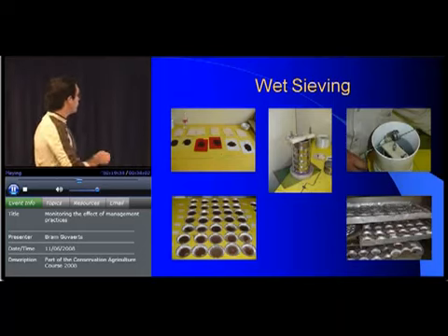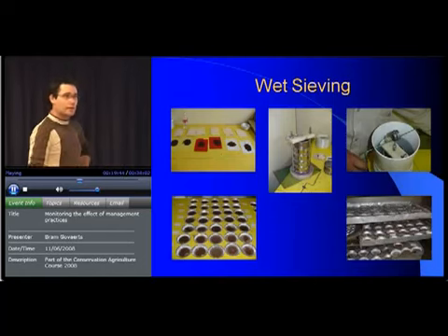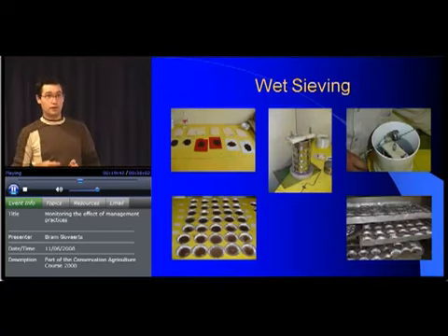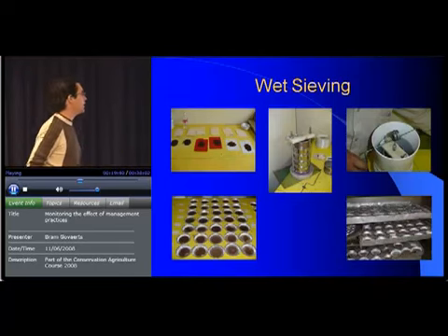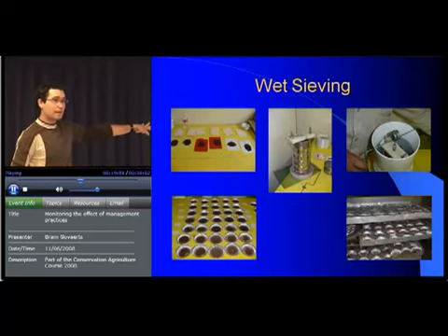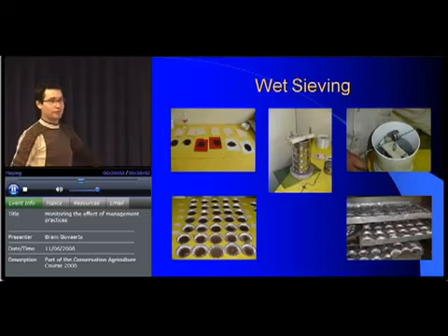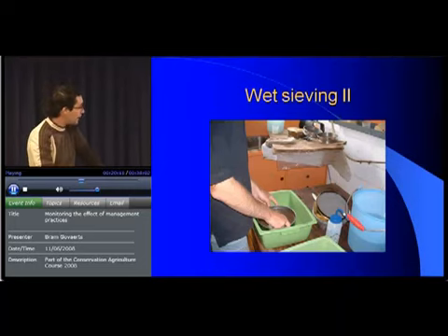So what do you do? You have the soil, you basically slake it, nest of sieve, you move it up and down, you put every sieve in a plate, you put the plates in the oven, you weigh the plates, and then you still have to do sand correction. So on all those plates, you disrupt, etc., etc. I will explain it to you in the lab. Now if you do this, it's better to do it over the weekend so you have the lab for your own, okay? Because you're going to produce lots of plates and use lots of space in the oven, right? But it's a beautiful thing to do. I really like it.